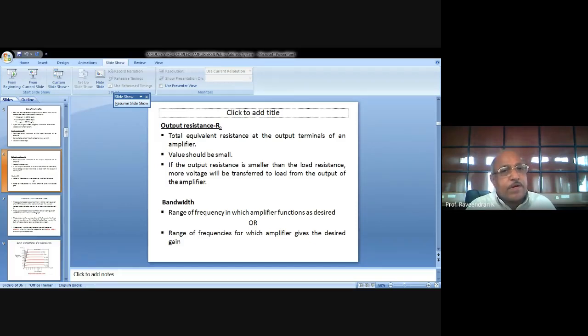Why do we say RC coupled common emitter amplifier? The common emitter configuration is connected with an RC network in order to bias, stabilize, and also to compensate for the signals and all those things. So certain bias conditions have to be satisfied. Of course, the system has to be biased before signal amplification. The common emitter configuration has to be biased properly by giving certain potential with proper polarities. That is what is called a bias, isn't it? So that particular biasing should be done before we operate it as an amplifier.